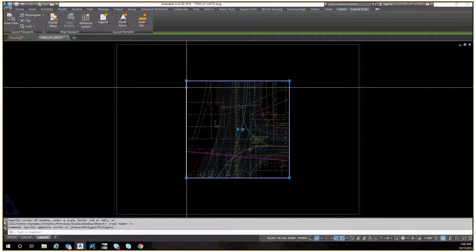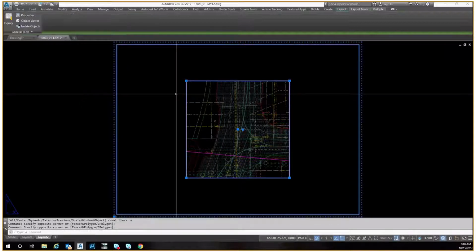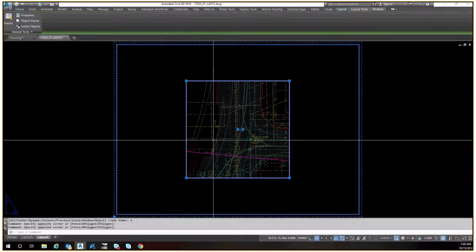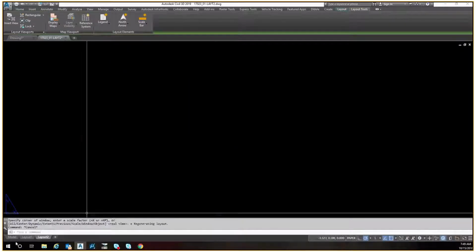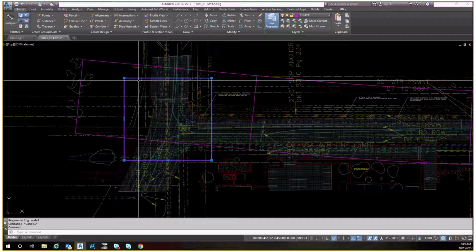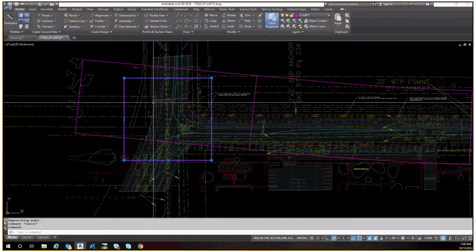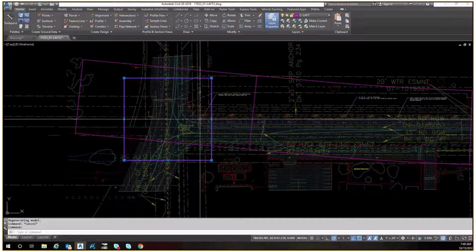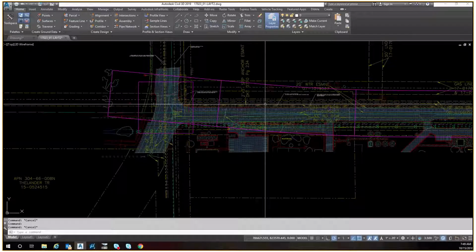And again, this should be on CView. Layers, don't pay attention to the layers necessarily of what I did with the sheet related stuff. But in a layout file, everything should be on C-LAYT, and you would really go into separate files for your exhibits and sheet creation in order to use this layout. But that's the basics of how to create a layout for either an exhibit or for your sheet production.